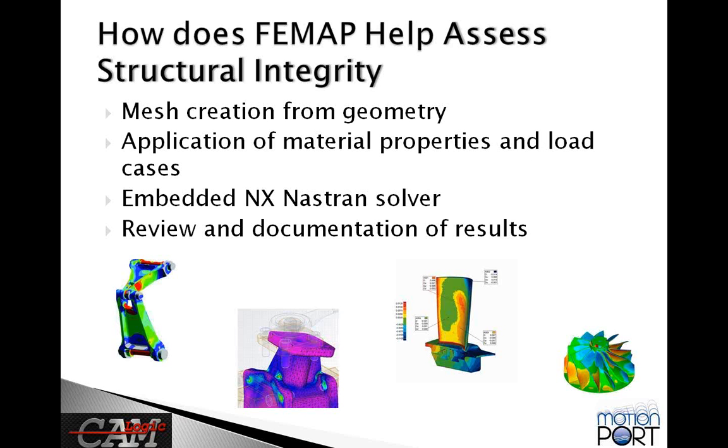And the powerful thing is that when we apply these conditions of the load cases, we are doing so from a geometry point of view, so that later if we decide to change the mesh, these applied load conditions do not have to be readjusted because they're defined with respect to the geometry, and then they're applied to the little finite elements that are created automatically.